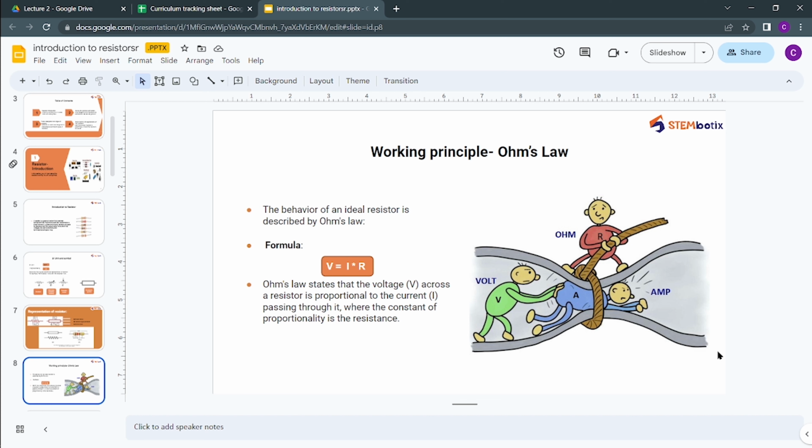If a breakdown or fault occurs in one branch of a device, it would not affect the devices in other branches, as the other devices are on a different branch. As you can see in this network, if the fault occurs in this section or this particular branch, the current has the other branch or other path to flow through. Hence, the components without the faulty section will remain turned on as before.